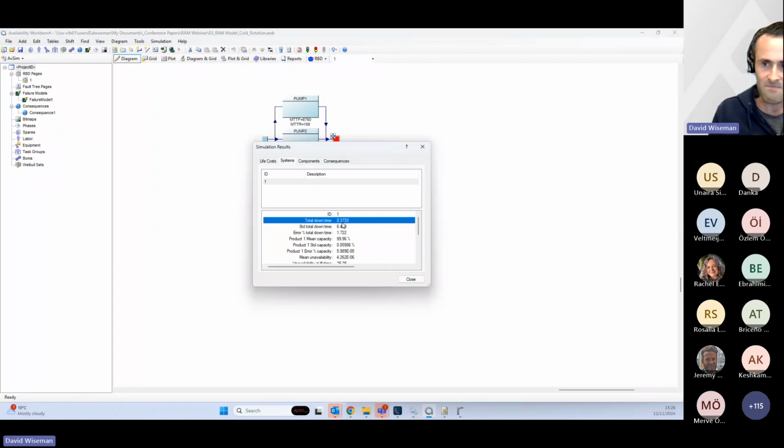So, like I said, telling the program that if one piece of equipment is failed, then that will become the new backup when we start it up again. We can also do things like change the failure rate of objects, change the MTTF of objects under different circumstances, change the maintenance behavior of objects.